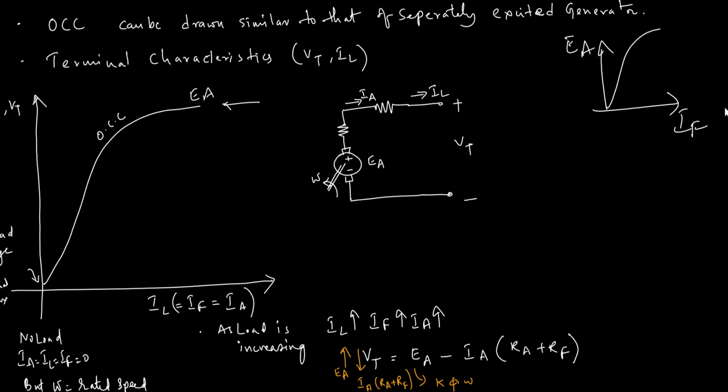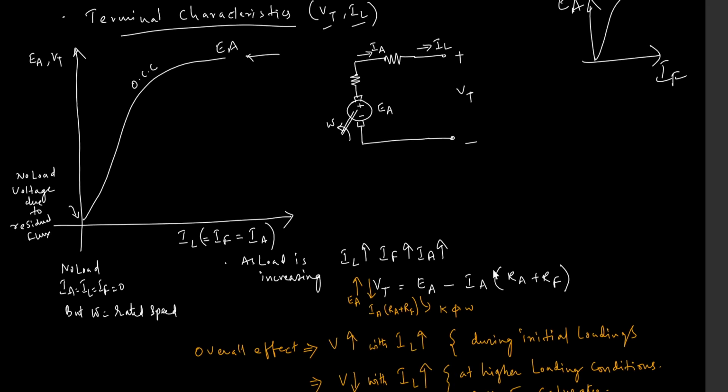But when it comes to the terminal characteristics, VT versus IL, before loading, the machine has to be started. It should be operating at no load conditions.